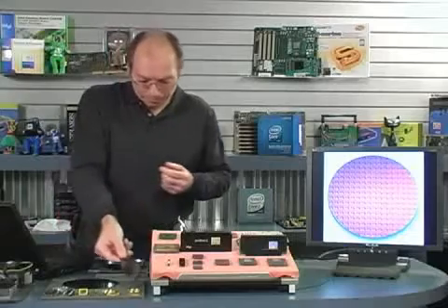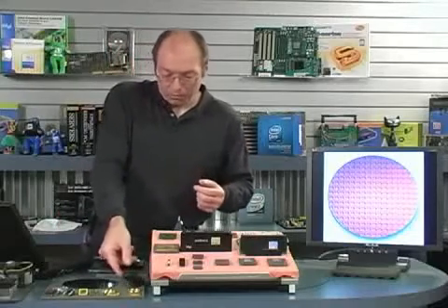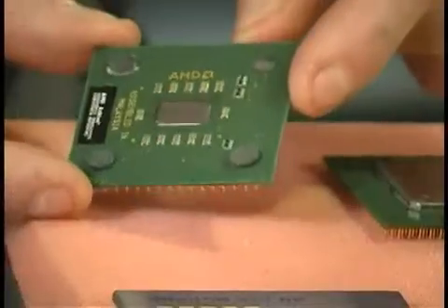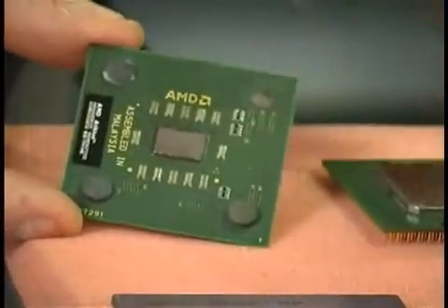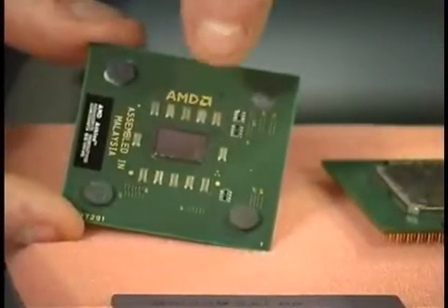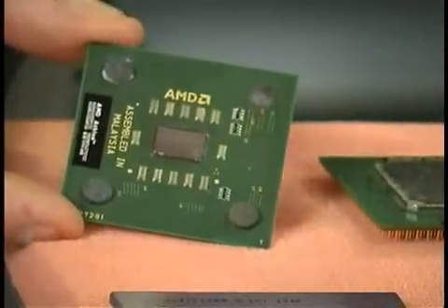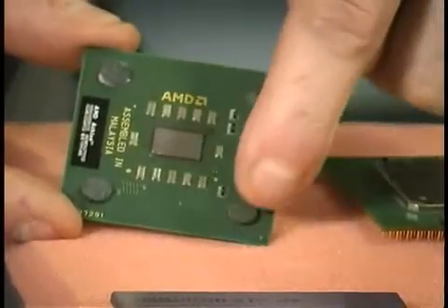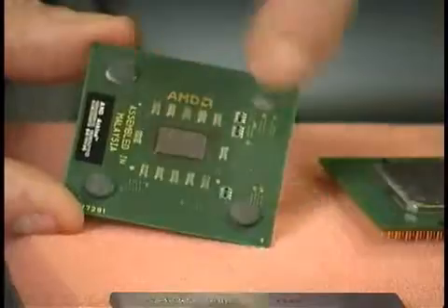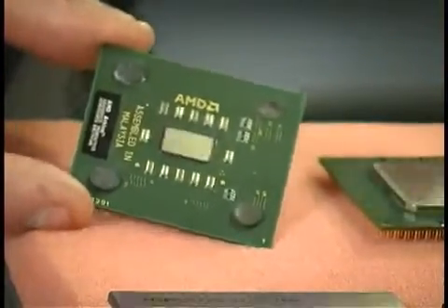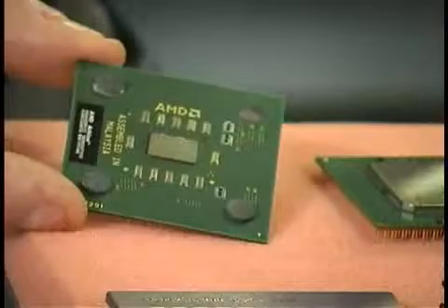It's very brittle. So what would happen was when you would put a heatsink on a chip like that, and here's an example from AMD. This is an AMD Athlon processor with the raw processor die sitting right in the middle of the chip there. If you put pressure on it, it would crack the die. What AMD did was put rubber pads around each of the four corners to try to mitigate that problem, but still it was happening all too frequently.